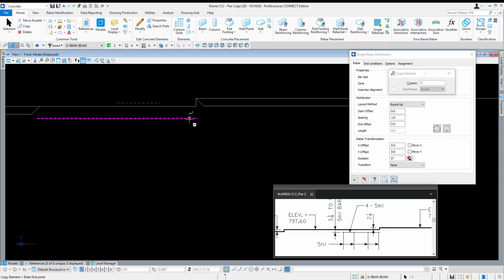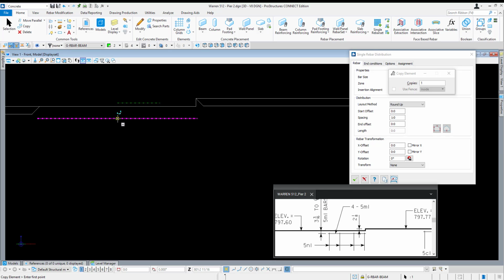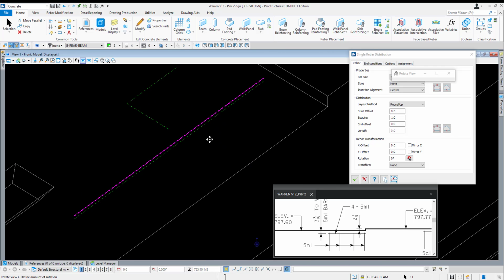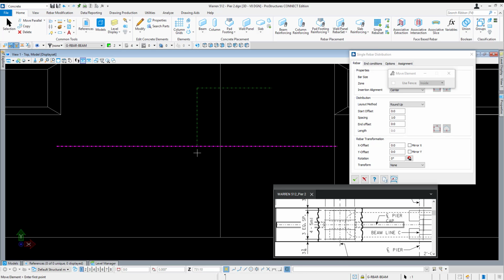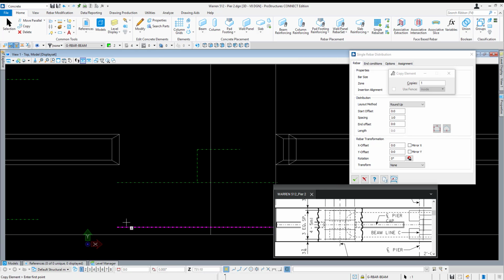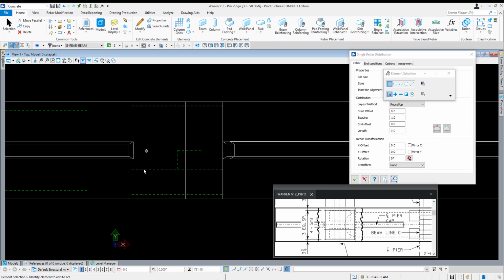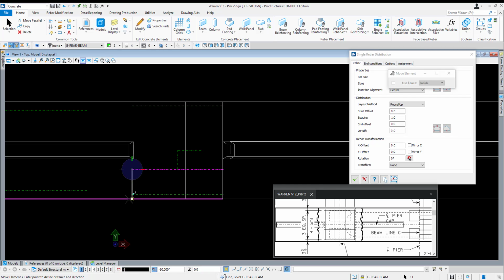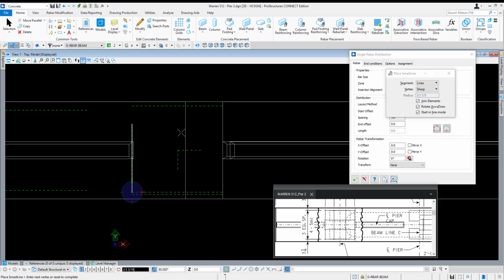And I know that my other direction bars need to be up just 5/8 from there because it is a number 5 bar. So let me go ahead and copy this up. 625. There we go. Now for these bars, they will need to be 2-inch clear from edge, so I'm going to go ahead and move that one back here. Minus 2. And copy it to the other end, subtracting out 2. Good deal. And this first bar is going to be 3/16 from the edge, so I'm going to go ahead and shift it back to here, minus 3 3/16. And we're going to take that all the way across times 2.